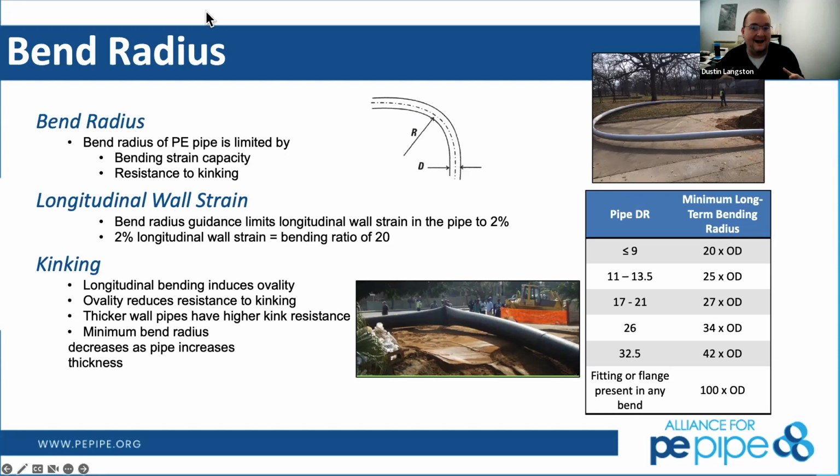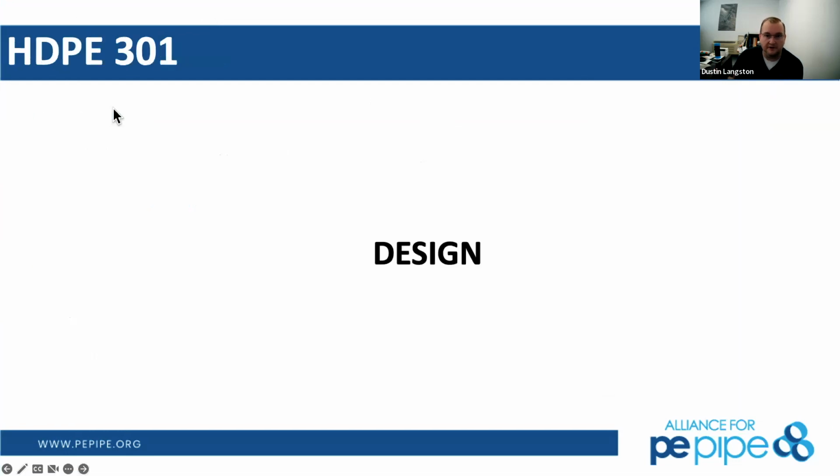You have to look at the way chlorine actually affects HDPE pipe, and it has to have a force behind it to cause that reaction for chlorine to degrade polyethylene. And so when you just have a pipe full of a chlorine solution, there's nothing there. There's no force there that's actually creating that reaction. And so if you had that drill string fully pressurized and chlorinated that whole time, then we'd actually have to look at it. We can take samples and we can figure something out. But most of the time when you're doing a chlorine test, you don't have it under pressure. You've just filled the pipe up with your chlorinated water and it's just sitting there. So in those times, nope, there's no issue at all.